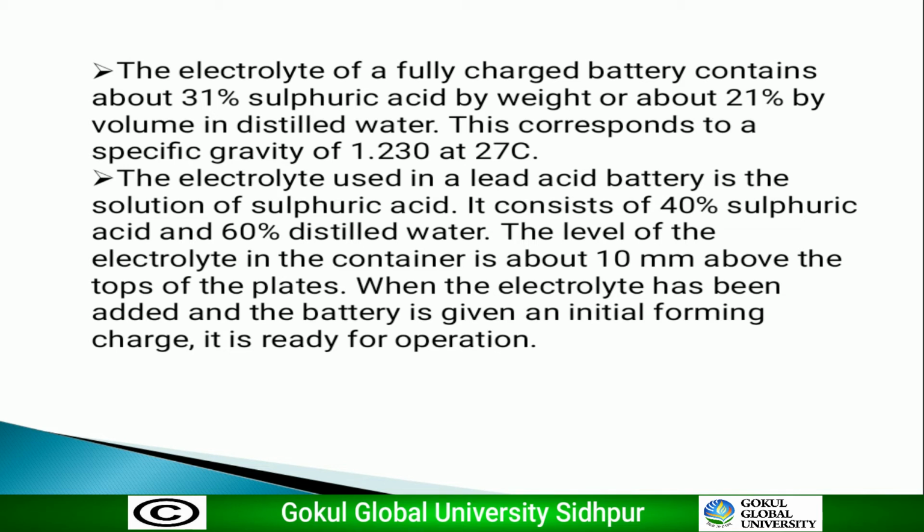Here is something more about electrolyte. The electrolyte of a fully charged battery contains about 31% sulfuric acid by weight, or about 21% by volume, in distilled water. This corresponds to a specific gravity of 1.230 at 27 degrees, atmospheric temperature.